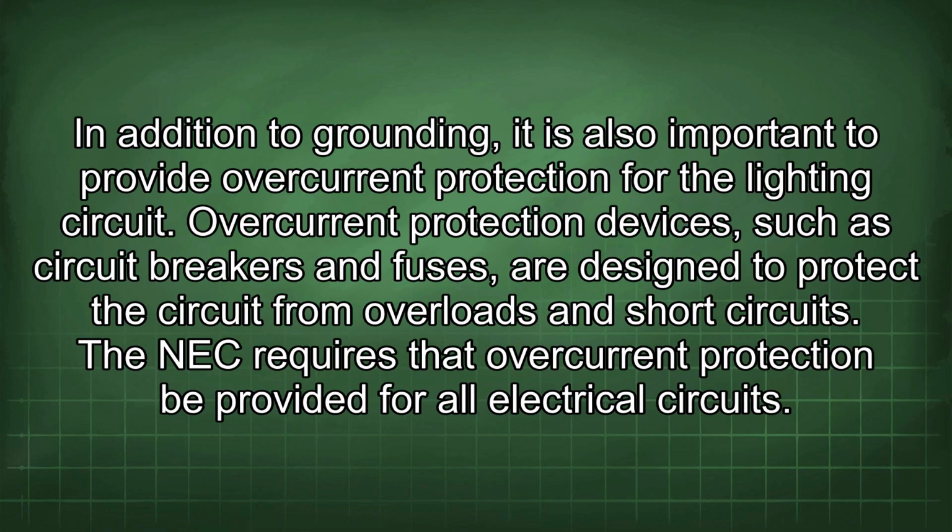In addition to grounding, it is also important to provide overcurrent protection for the lighting circuit. Overcurrent protection devices, such as circuit breakers and fuses, are designed to protect the circuit from overloads and short circuits. The NEC requires that overcurrent protection be provided for all electrical circuits.